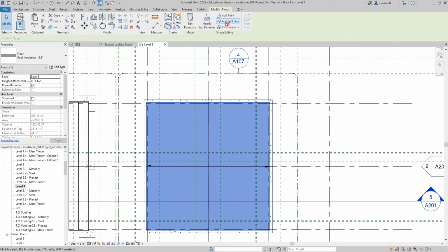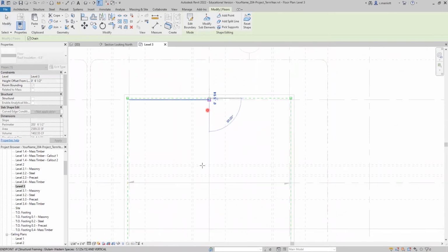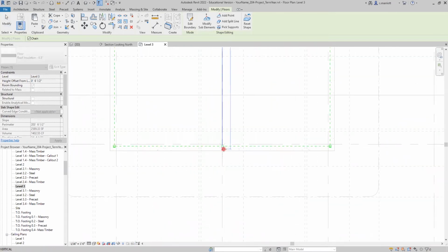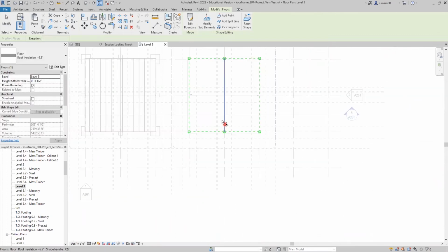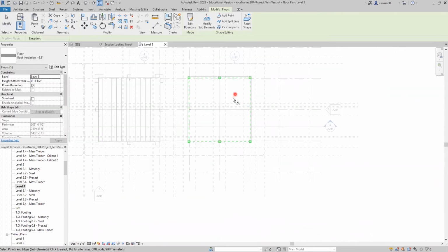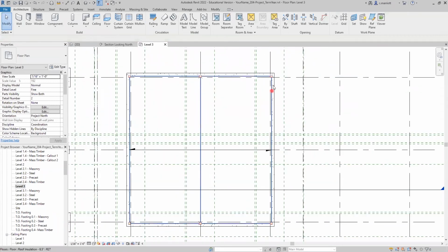Okay, so what we'll do is we'll add a split line right down the middle, from there to there. Okay. Now there's basically 2 areas of the roof, and we'll put one drain on one side and another drain on the other side. Now, before I do that, I'm going to click on the modify tool, and so I can leave that. And as I hover over that floor assembly, you can see there's now a split down the middle of it.